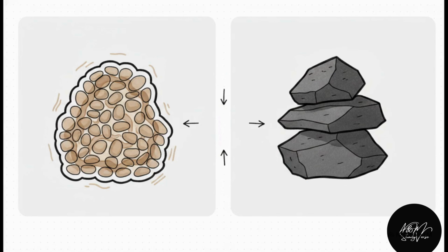And the resistance to that sliding, that shear strength, boils down to two main things. First, we've got cohesion, represented by the letter C, which acts like a natural cement, binding clay soils or intact rocks together. Second, there's the friction angle, represented by the Greek letter phi. This is all about the physical interlock, the grinding friction of larger particles like sand and gravel. If you want to stop a landslide, you're relying entirely on these two properties holding the line.